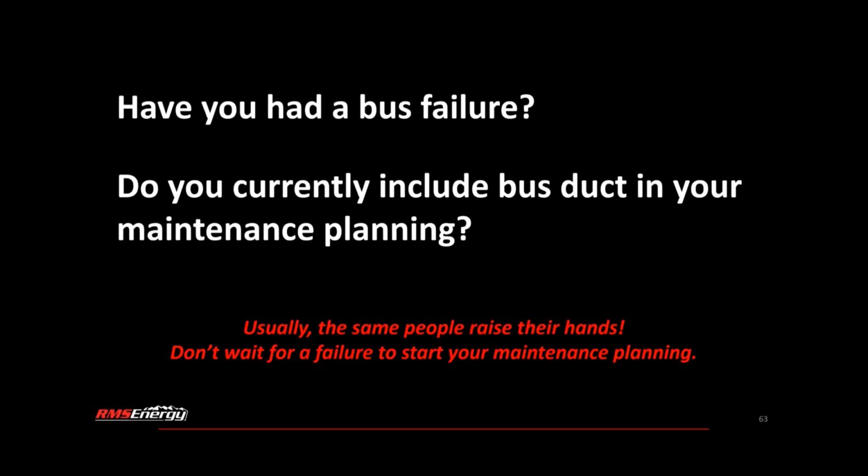But as far as investigating what the source is or what's causing it, that can be a pretty in-depth process. It just depends on the type of design of the bus, what kind of support steel you have around it, and verifying that you have proper isolation of your bus duct if it has isolated connections from your support steel.